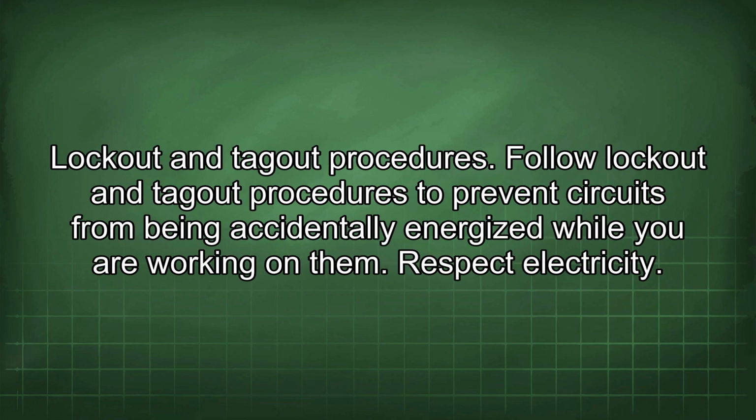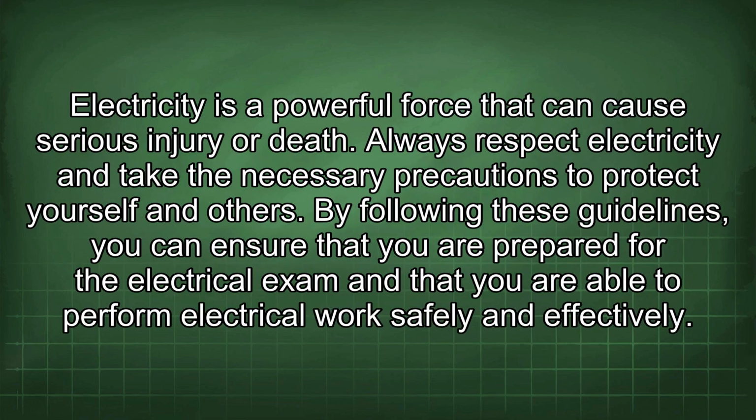Lockout and tagout procedures. Follow lockout and tagout procedures to prevent circuits from being accidentally energized while you are working on them. Respect electricity. Electricity is a powerful force that can cause serious injury or death. Always respect electricity and take the necessary precautions to protect yourself and others. By following these guidelines, you can ensure that you are prepared for the electrical exam and that you are able to perform electrical work safely and effectively.